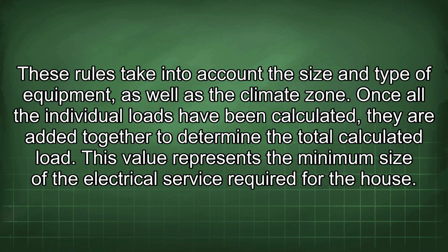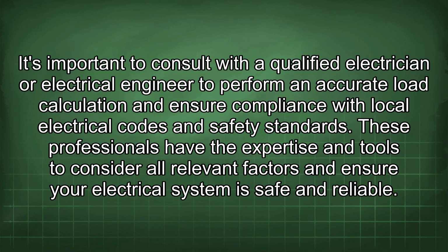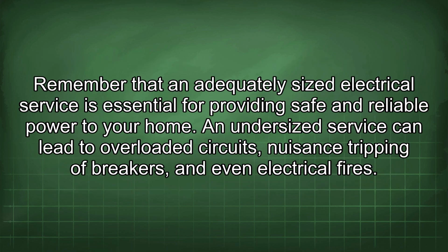Once all the individual loads have been calculated, they are added together to determine the total calculated load. This value represents the minimum size of the electrical service required for the house. It's important to consult with a qualified electrician or electrical engineer to perform an accurate load calculation and ensure compliance with local electrical codes and safety standards. These professionals have the expertise and tools to consider all relevant factors and ensure your electrical system is safe and reliable. Remember that an adequately sized electrical service is essential for providing safe and reliable power to your home.